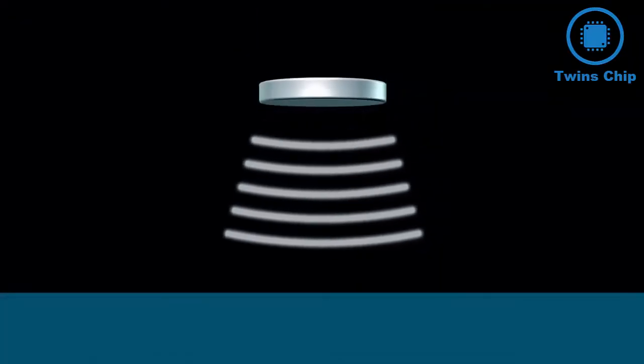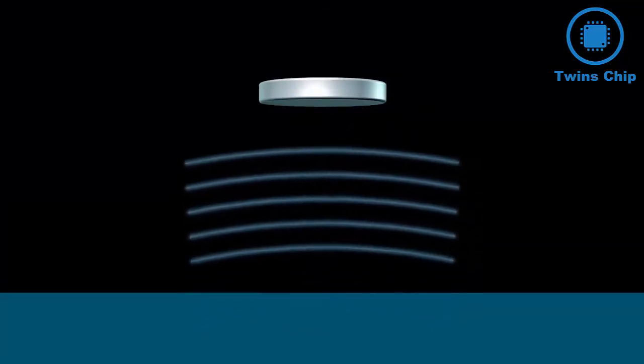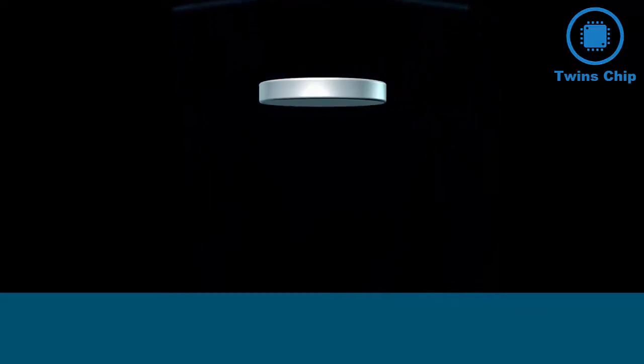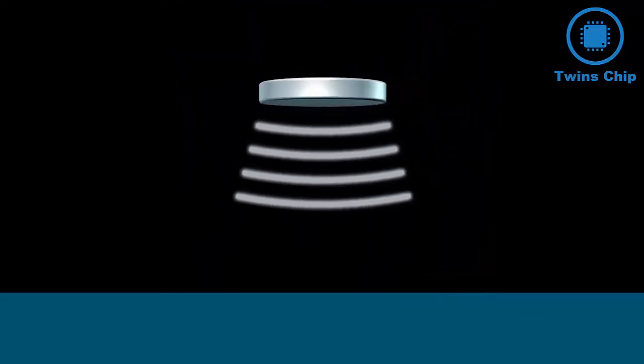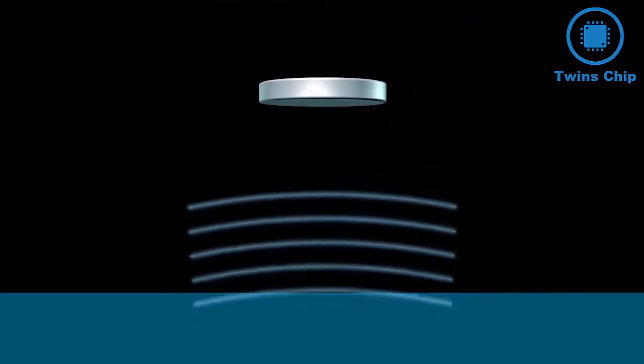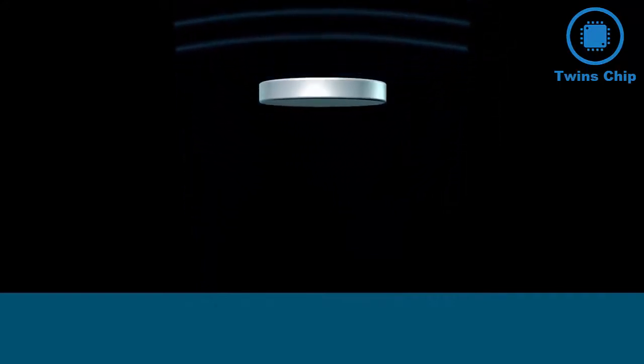Ultrasonic waves are mechanical waves. Ultrasonic pulses are generated piezoelectrically and reflected on the medium surface by the density change between air and the medium. The period of time measured and analyzed by the instrument between sending and receiving the pulse is a direct measure for the distance between the sensor membrane and the medium surface.